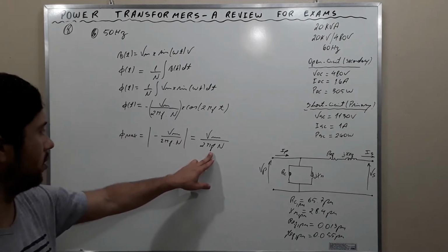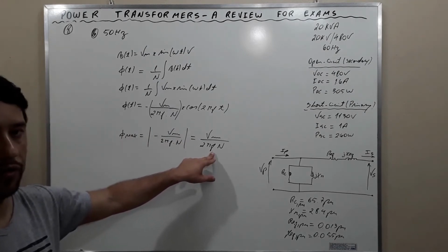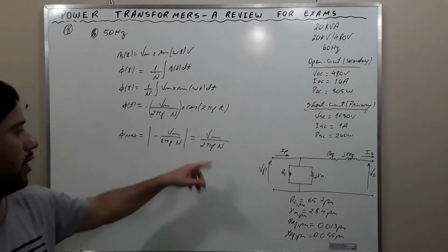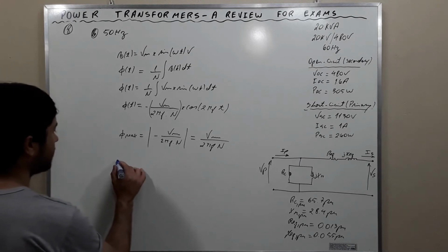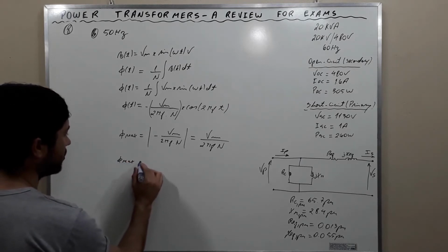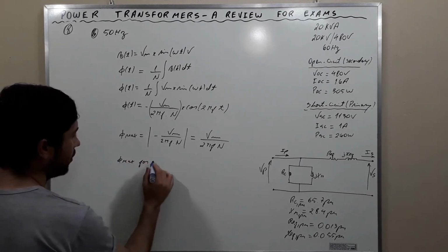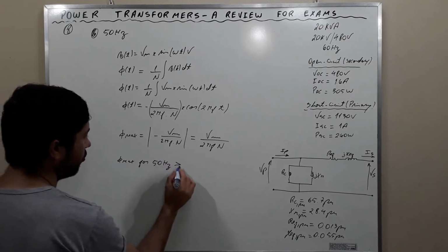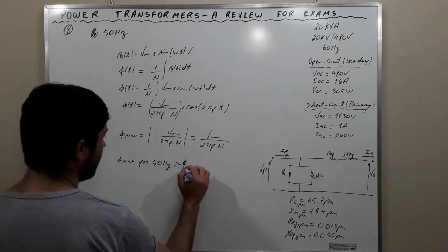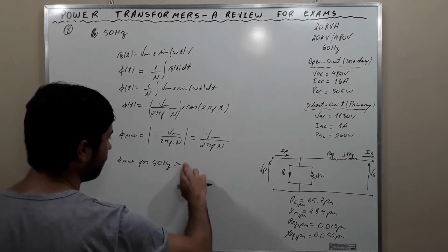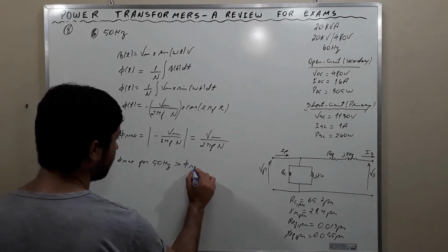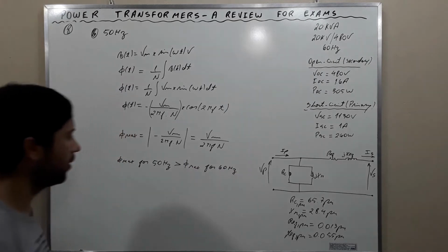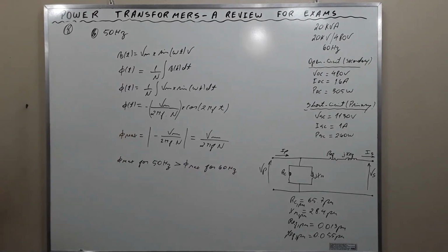If we increase the frequency, we decrease the flux. This is our conclusion. So the maximum flux for 50 hertz is greater than the maximum flux for 60 hertz. Okay, this is our conclusion.